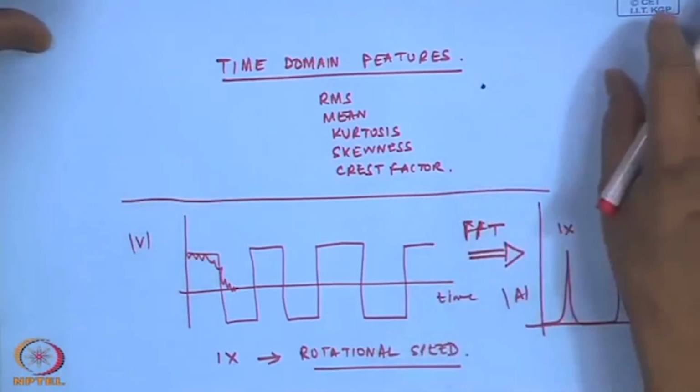And you will see, again one thing I should drive home, that in vibration monitoring, whether in the laboratory or in the field, it is essential and implied that you are always measuring the rotational speed. It is a good practice. Many times when you go to the industry, people assume this machine is running at 1440 RPM or 2900 RPM, etc. That is fine. That is what the motor rating says. If we have no other knowledge about the speed of the machine, that is good to follow.